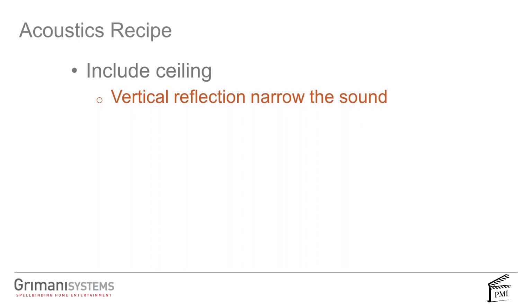So to your point earlier, you expect a really high-end projector with a high contrast ratio, and it behaves barely better than a commercial presentation projector that costs 1/10 of the price, and is 1/4 the size. Ultimately the client's looking at a poor picture and is not happy. So don't forget to treat the ceiling for both dark tones in the video, and acoustical absorption and diffusion.